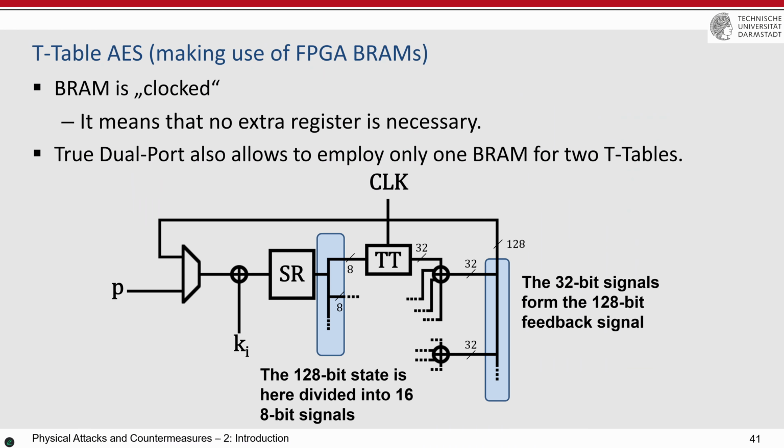Yeah? And if it's like this, you see here the T-table-based implementation using BRAM: shift rows is there, and the T-table, and then XORs, and then the concatenation of them, and then bringing back to here. But what is important, you don't need any register anymore, because the block RAMs have the register inside. Every time that you want to read from the lookup table through the block RAM, what you need to do is to give the clock. It means that 1 clock latency is the minimum, and you don't need the register at all. Similar to the round-based implementation, you can have the T-table-based implementation on the FPGA, and it's also clocked, as I said.